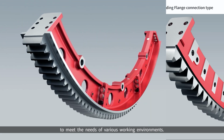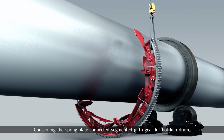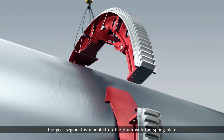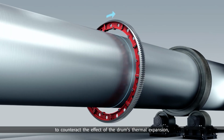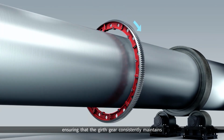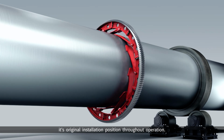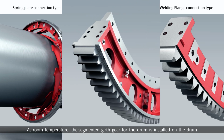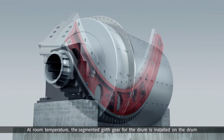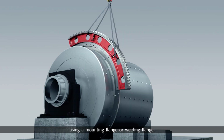Concerning the spring plate connected segmented girth gear for hot kiln drum, the gear segment is mounted on the drum with the spring plate to counteract the effect of the drum's thermal expansion, ensuring that the girth gear consistently maintains its original installation position throughout operation. At room temperature, the segmented girth gear for the drum is installed on the drum using a mounting flange or welding flange.